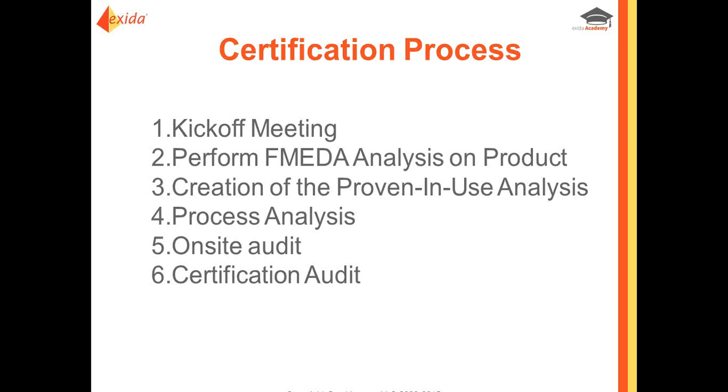And that audit is taking every requirement in IEC 61508, line item by line item, and making sure that the process and the product meet all of the requirements for 61508. And at the end, we create a safety case, which is our tool for comparing the requirements to the product and the process that we're now analyzing. And once the certifying assessor is finished, they hand it off to a second assessor. They go through then and double check that all of the requirements were met. So we have 2 people checking off on it.